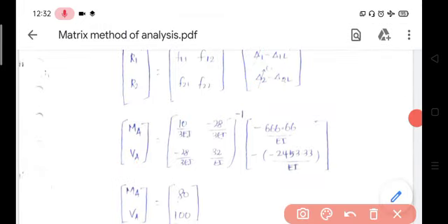Our first redundant is moment, bending moment. Second redundant is vertical reaction, MA VA. Then flexibility matrix we already know. Substitute this flexibility matrix. Then delta 1 net deflection at the assigned coordinates are 0. So, therefore, the delta 1, delta 2 are 0, delta 1L and delta 2L is already known. Okay. So, previously we determined these two values. So, delta 1L is equal to 666.66, then delta 2L is equal to minus 2453.33 by EA.